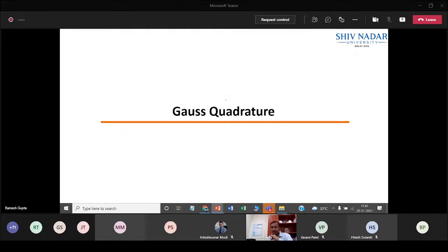All right. Now I would like to introduce one more concept, which is called Gauss Quadrature. Basically, for example, you have the stiffness, which is usually represented in this form, with some dx. Let's say you want to find the stiffness of a line element, or a bar element. The stiffness of the element is given by the strain displacement matrix B, the constitutive matrix C, and again the B matrix, which is the kinematics matrix. Together, if I integrate over the domain, I get the stiffness matrix K.